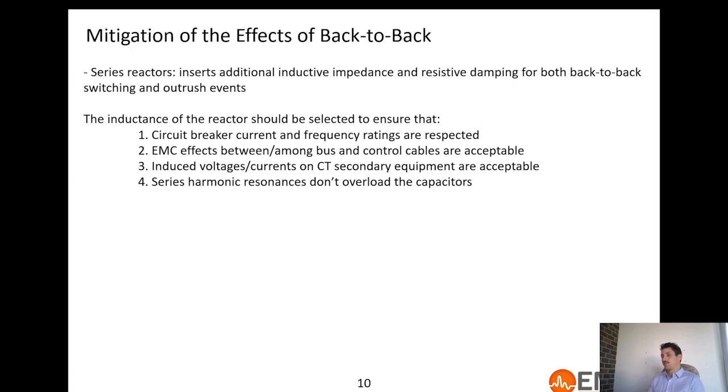You also have to take a look at your measurements. The cap bank and the breaker may withstand a certain frequency and current, but it has to be the case also for CTs and VTs, which are sensitive devices and typically don't really like high frequencies.